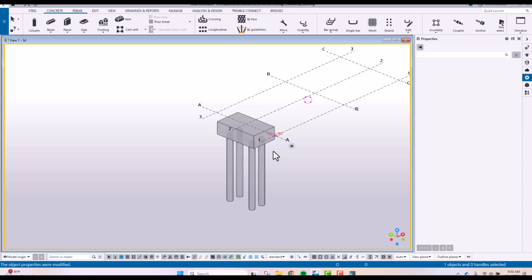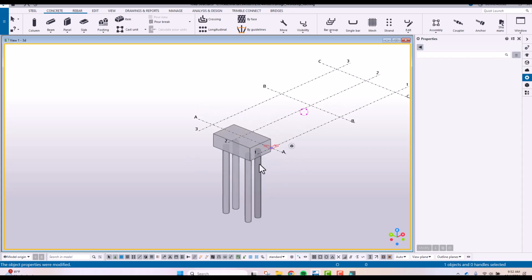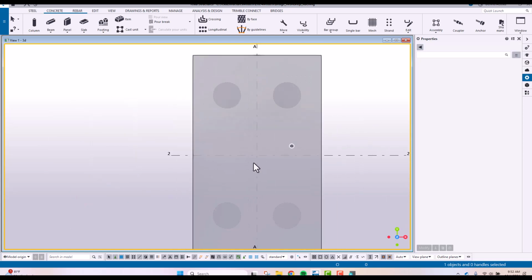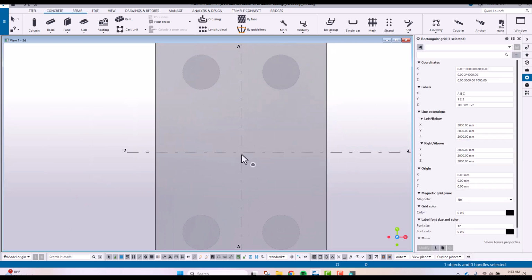So for the pier, now let's create that oval. I just want to show you how to use the reference point, or construction point, and construction line. But again, as I'm telling you, there are different ways. This one is the basic.